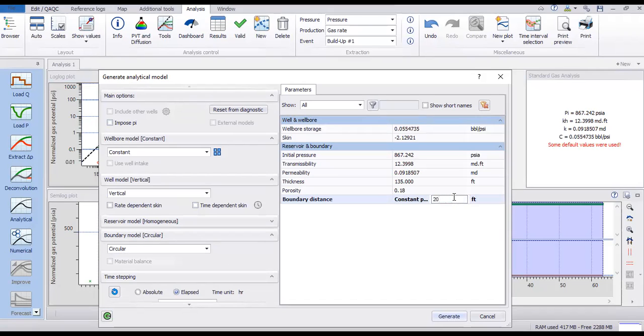Okay, maybe the well is located very close to a water injection well, right? So after the pressure transient meets the incoming water, and the incoming water can be assumed as a constant pressure source, then the derivative declines, drops to zero.